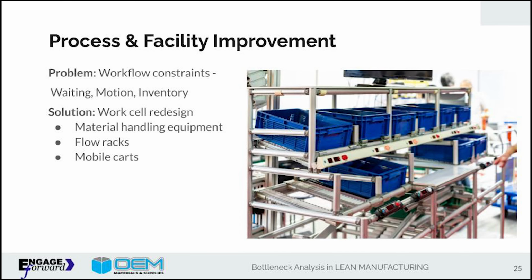And it is workflow constraints. Again, we're talking about the work cell, the waiting, the motion, the inventory. The work cell is designed for a particular process, and you want to centralize all the resources in that place. You start with the workstation, and you provide all the tools with the shadow boxes or peg boards. You optimize that workstation.